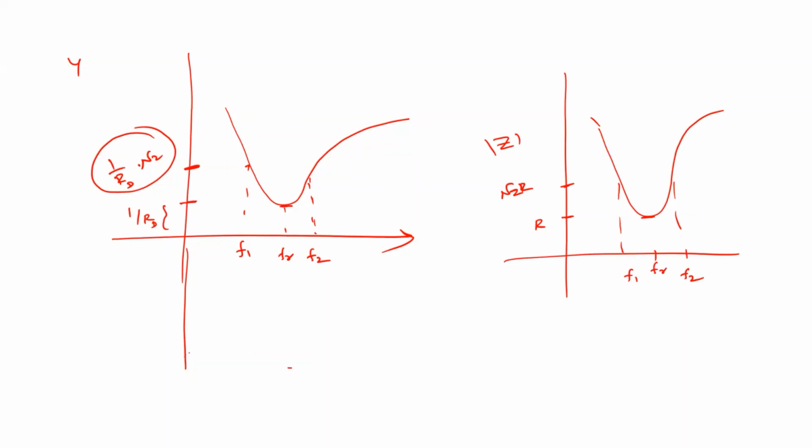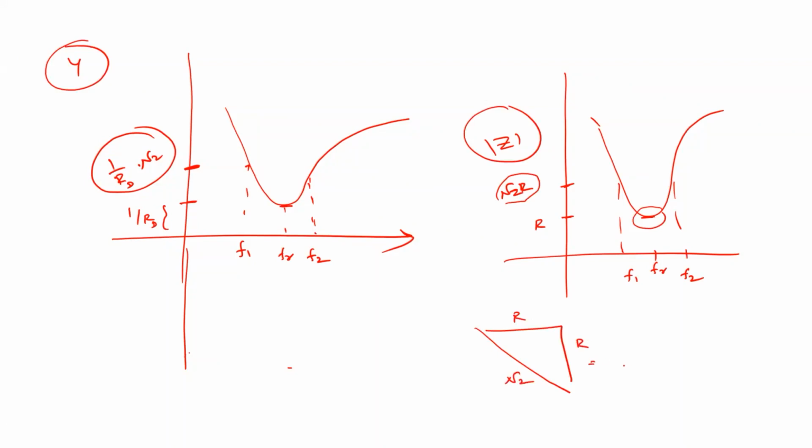So here the thing is that this is an admittance, so this is impedance only. So this is the minimum possible, right? So this is where the imaginary part is equal to the real part. We have derived this, right? So this is R, this is also R, and this will be root 2. Where omega L minus omega C, this value we equate to R, right? Yes, sir. Got it, sir. Now understood. So everything is the same, because both are analogous, right? Earlier you had impedance, now you have admittance. The rest of the things are the same.